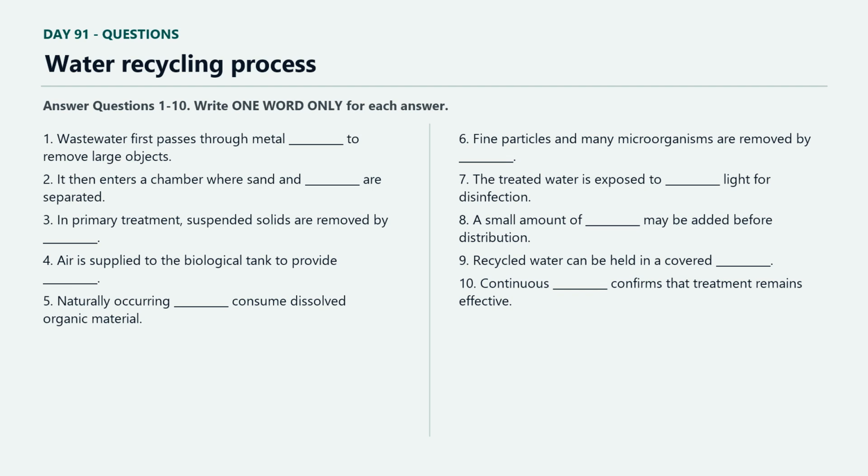Ultraviolet treatment is effective at the point of exposure, but it leaves no lasting disinfectant in the water. For this reason, a small amount of chlorine may be added before storage or distribution. This residual limits microbial regrowth if the water remains in pipes for an extended period. The dose must be controlled because too little provides inadequate protection, while excessive treatment affects taste, materials, and byproduct formation.